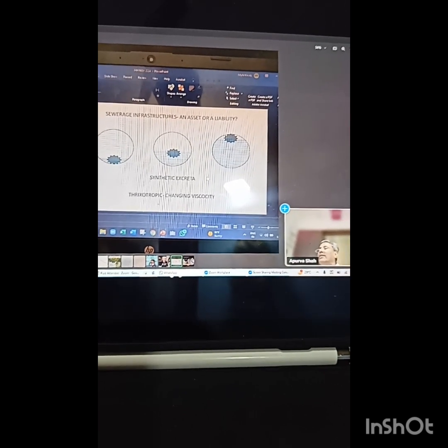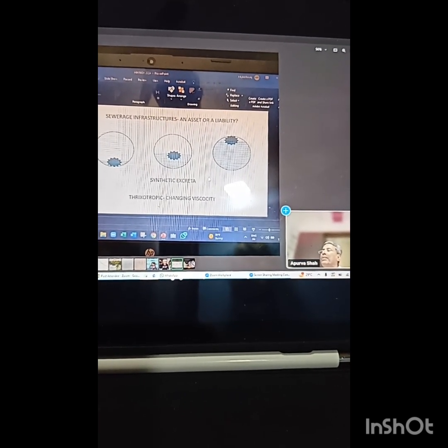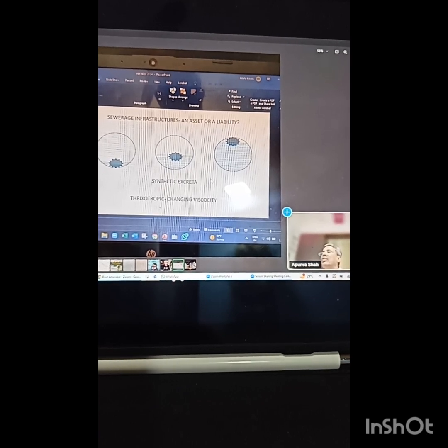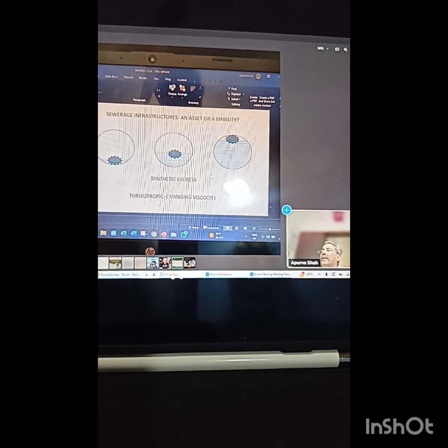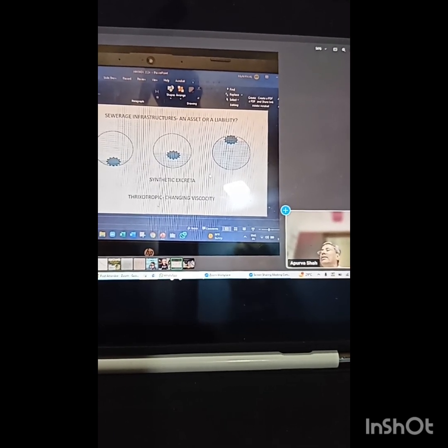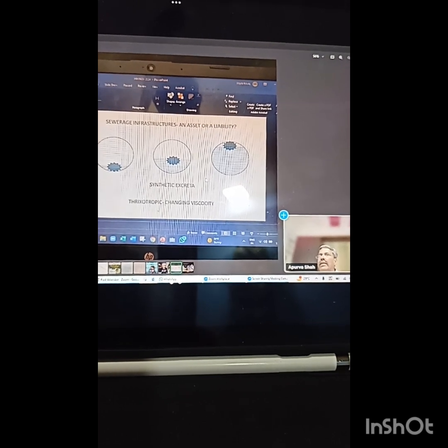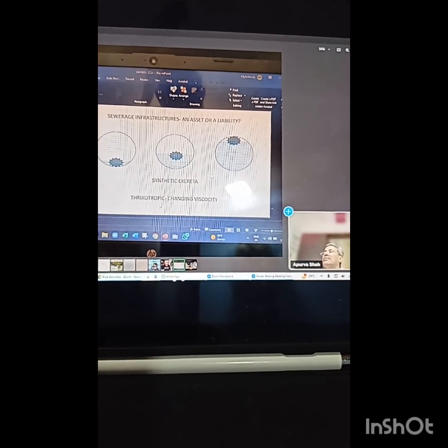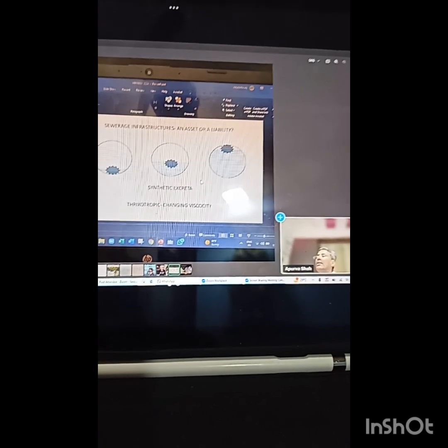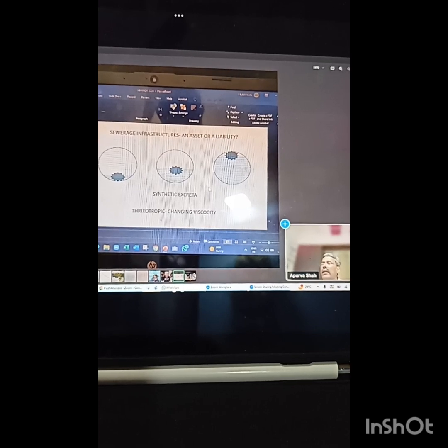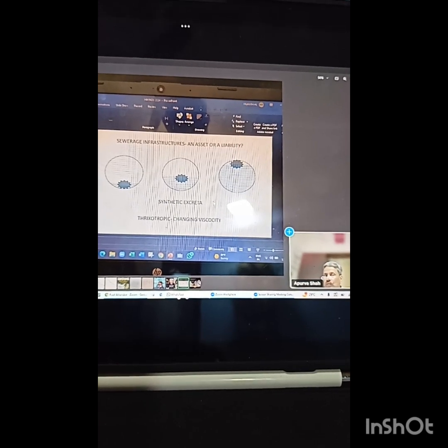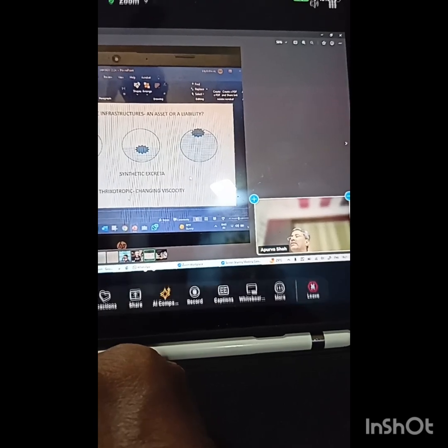But line carry is very, very important, which we have also partially discussed with less flow, which we are doing right now with the WCs, a 4 liter or a 6 liter flush. The solids can reach maximum up to 18 meters. Considering all push and every day push, it can reach up to maximum 18 meters, not beyond that. So that is another issue, how to do that and how we can take care of it. That is something we need to look at. So that point we need to address as far as flow is concerned.